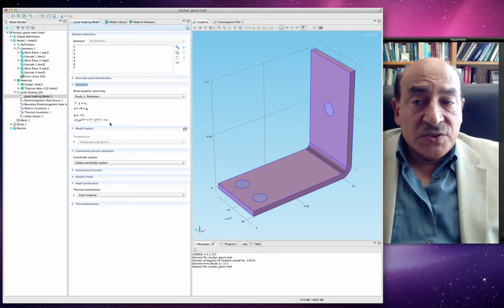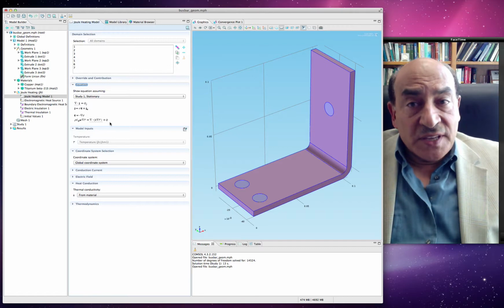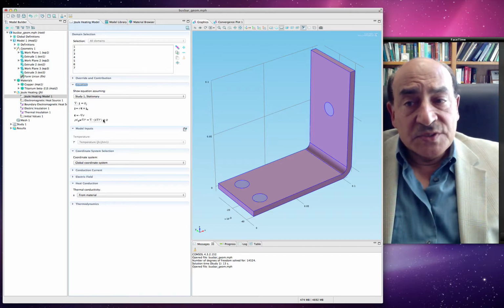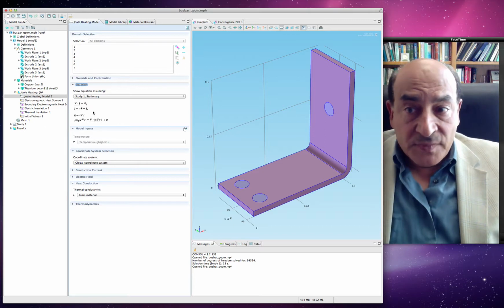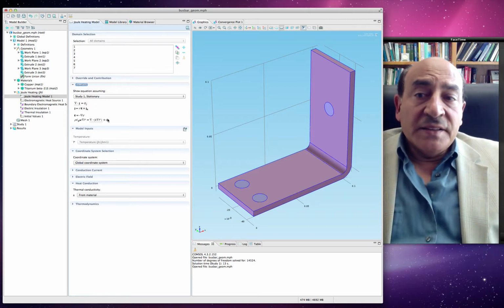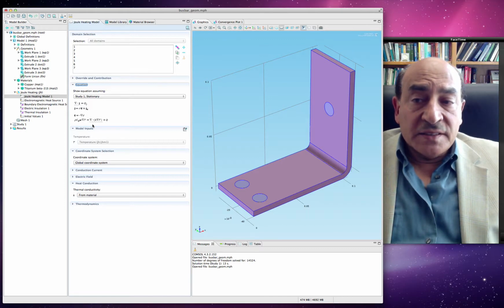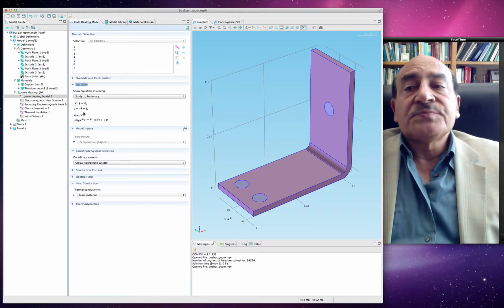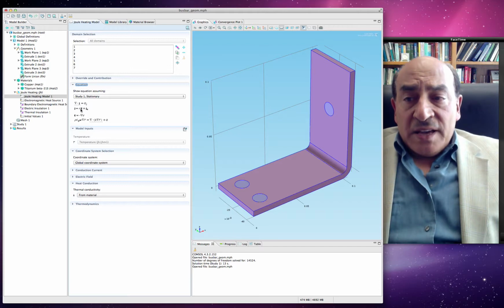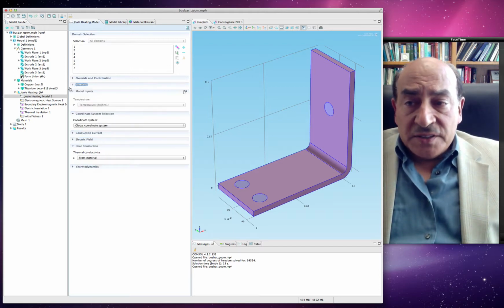And the heat source Q is actually the Joule heating that we are talking about, the I squared R. And that comes from coupling with the equation for electric current conduction. So that's basically the idea behind these two equations. The top one is underlined and the bottom one is underlined, and then the two in between are just kind of relationships that take you from one to the other one. So now we have understood the equation.